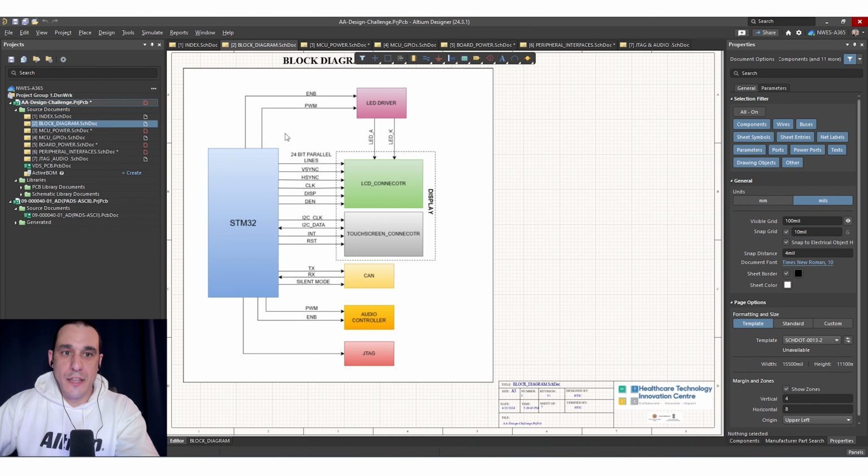And then here on page 2, we have a block diagram. You can see here that this block diagram shows that the design has been updated to work with STM32. Now, using STM32 allows us to do two things. Of course, we can interface with some of the original circuitry, but it also allows consolidation of a few things in the original circuitry down into the microcontroller, and that eliminates a couple of components.